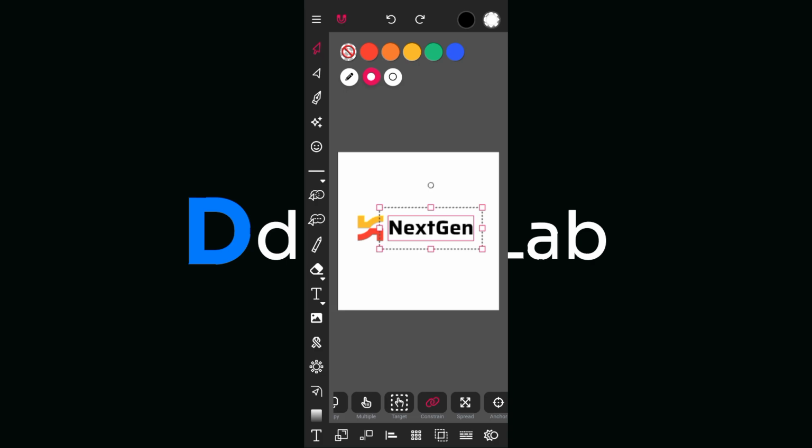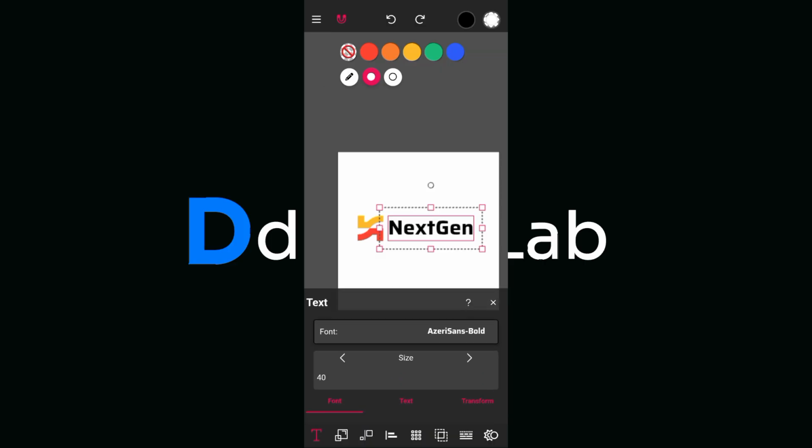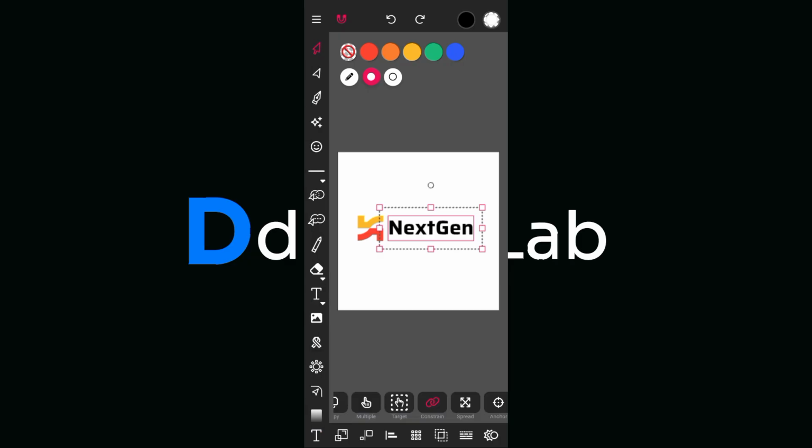Then we have this. So if you now want to change the typeface, once you click on this text, the last text, click on it, the last T icon here. You look at this left line on this list, there are two letter T's. The one with a drop down arrow is not what you are clicking on.